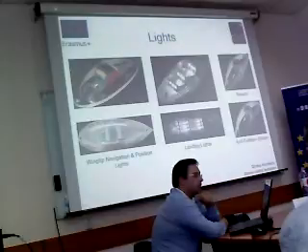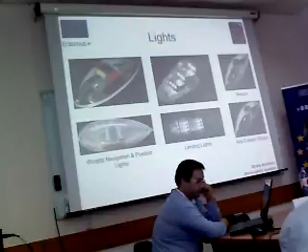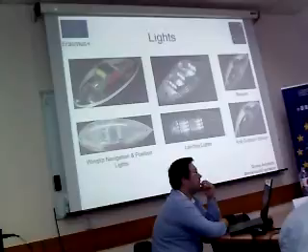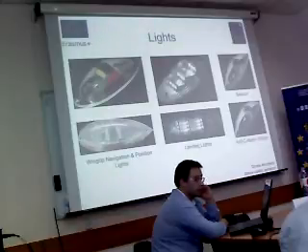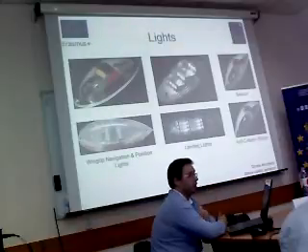So the beacon light can be found with a simple fade flash pattern of approximately 1 Hz. And the last lights are the anti-collision strobe that provides a 600 lumen flash of light, also at approximately 1 Hz. And it can be viewed for 230 degrees around the aircraft.